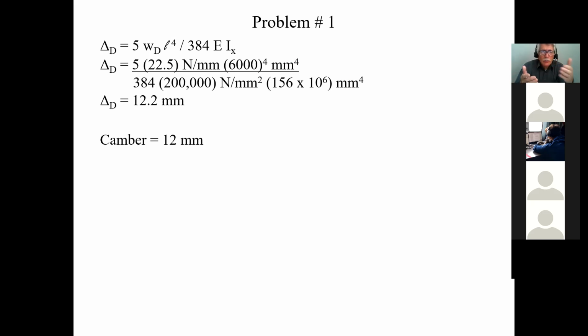Yeah, your beam is stiff, but, for example, L over 360 is a fairly stiff beam, and a lot of times that's what can actually govern the choice. But let's say I have a situation where deflection is not an issue and I want to keep it to L over 180. That's a relatively big deflection.